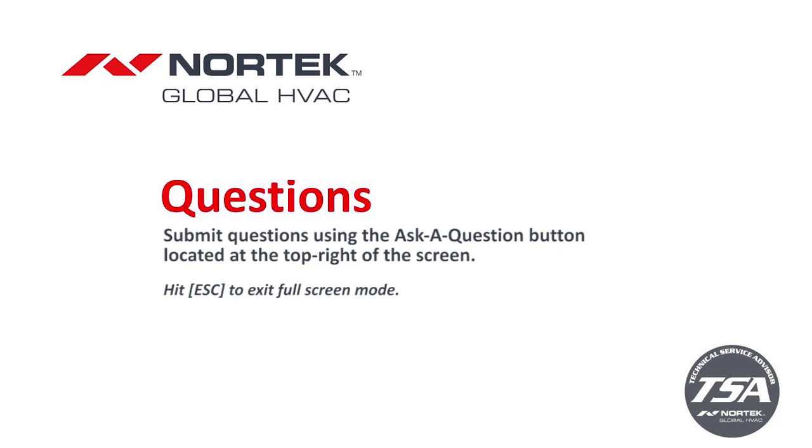Okay, all right, another question from Mr. Jerome. Can we use the calculator for heat pump mode? The calculator is only for cooling as of right now. I'm not sure if they're going to do a heat pump mode application, but it's only for cooling. Also, you can block the condenser off in cooling mode down to a 35-degree ambient temperature.